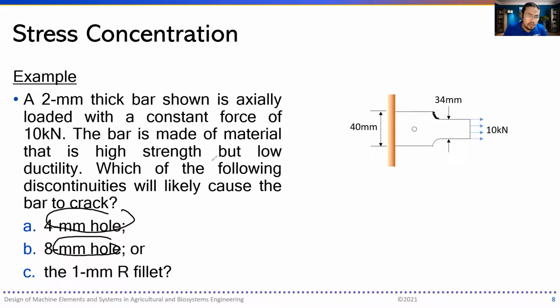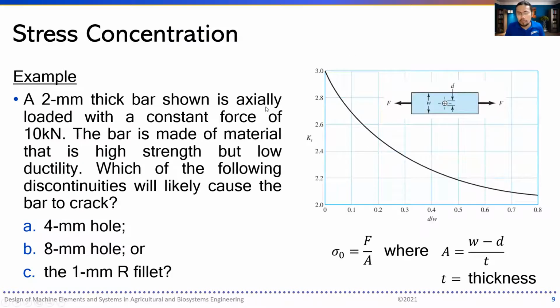So to solve for this problem, it is important to take note of the axial load. To solve for the stress along the axis, it's just the force over the area, and the area is going to be what? The width minus the diameter, times the thickness.